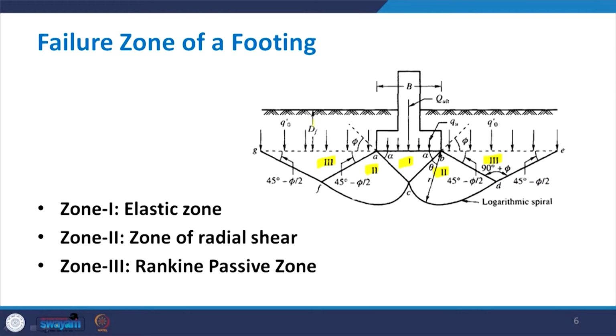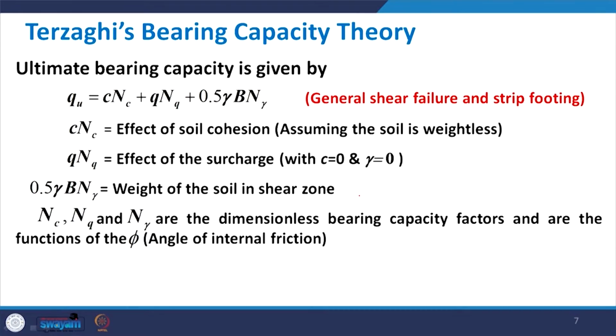Here for this footing, you have Df, which is nothing but the depth of the footing. This point is called the ground level. Below the ground level up to the base of the footing, which is this line, is called Df, and this is typically a very important dimension for any footing, while the width of the footing B is at the base. Another thing you can see in this slide is the angle alpha, and then the angle 45 degrees minus phi by 2, where phi is the angle of internal friction of the soil. So, with all these details we go ahead and continue with Terzaghi's theory.